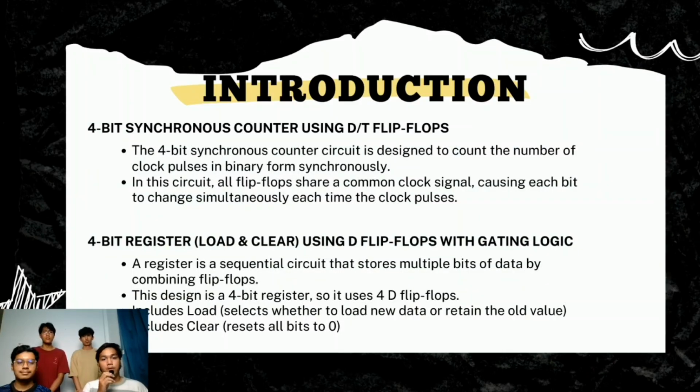Introduction. 4-bit synchronized counter using D or T flip-flop. First one, the 4-bit synchronized counter circuit is designed to count the number of clock pulses in binary form synchronously. In this circuit, all flip-flops share a common clock signal, causing each bit to change simultaneously each time the clock pulses.